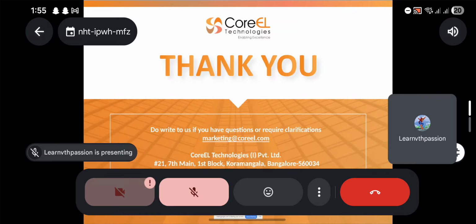Verification will be done through that. What is the difference between this verification and functional verification? Calibre is a complete analog verification. Functional verification is for the RTL. RTL is completely different, analog is completely different. There is digital, and this is analog. Here you are doing transistor level design, you are building the circuits. You are not writing any RTL code.